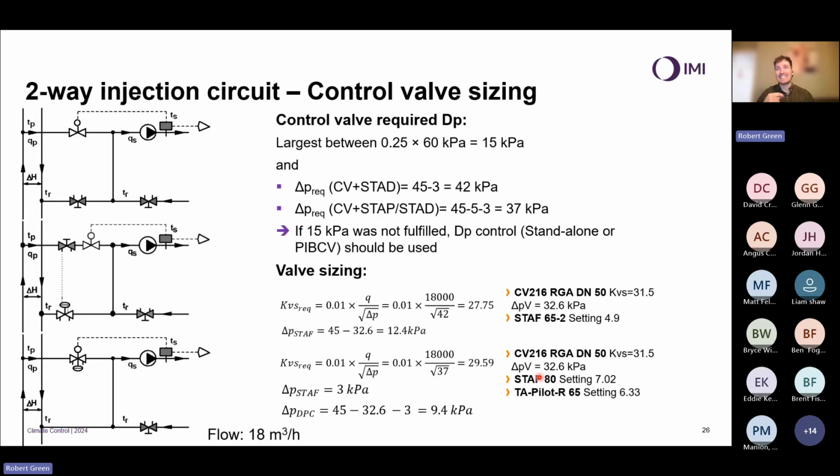So in this exact example, we can see the reality is we won't have much improved our control valve authority, and we'll see in the next slide how, with the addition of a differential pressure controller, the reality is we'll have bought an additional piece of equipment and not had a big influence on cost, but actually not really improved it.